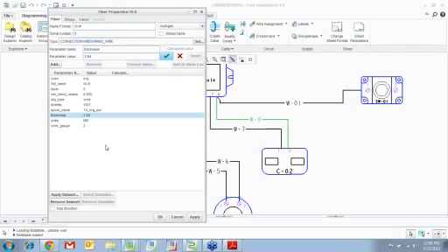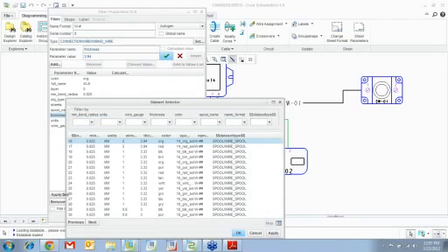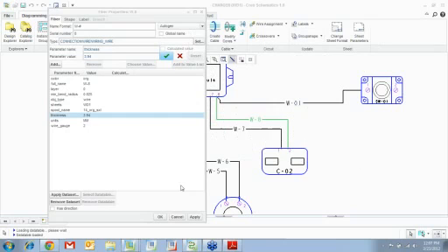Now, instead of manually entering all these values every time you create a wire, you can load a bunch of Excel files as data sets. Once you have that, you can go to a data set, apply a data set, and pick whatever you want: different color, different wire gauge, different thickness. You say okay, and that will be applied to that particular wire.